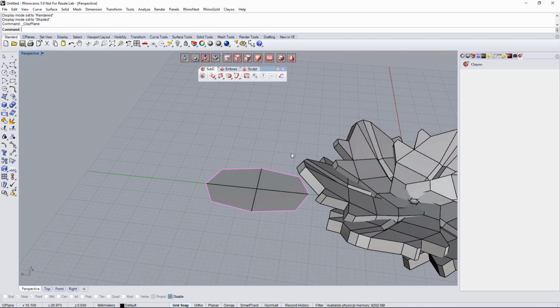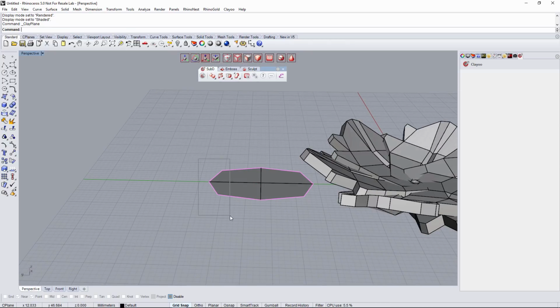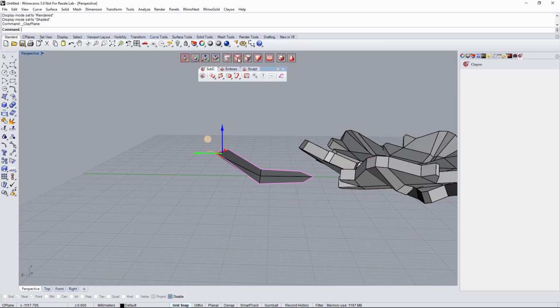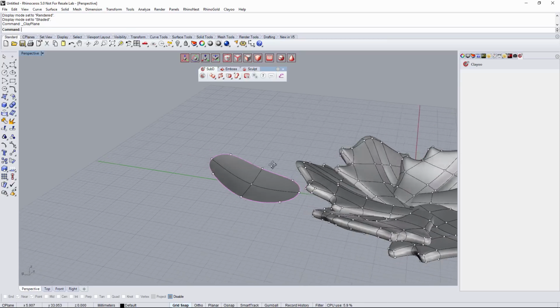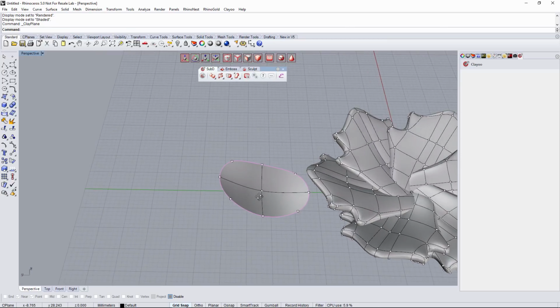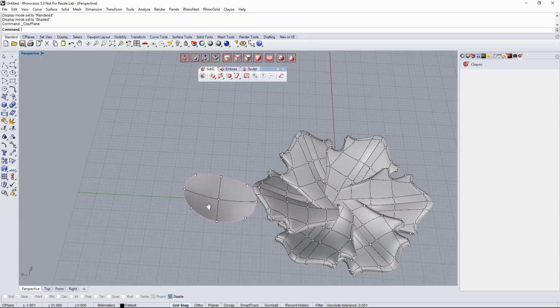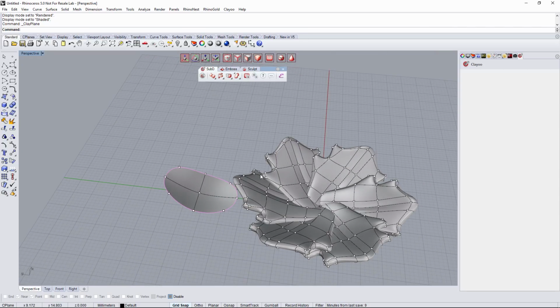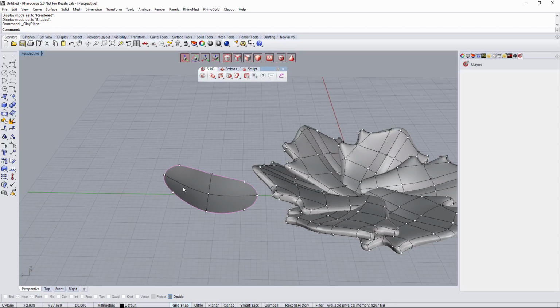Right now, if I display it in the basic view, I'm going to move these edges up. So grab these edges and move them up a little bit like this. Okay, and I will grab the inner point there and move it a little bit down. So something like that. And when I smooth that, that's a really basic shape, but it's what I'm looking for. So this one is a complex shape outside, so I'll create some inner simple faces in here.